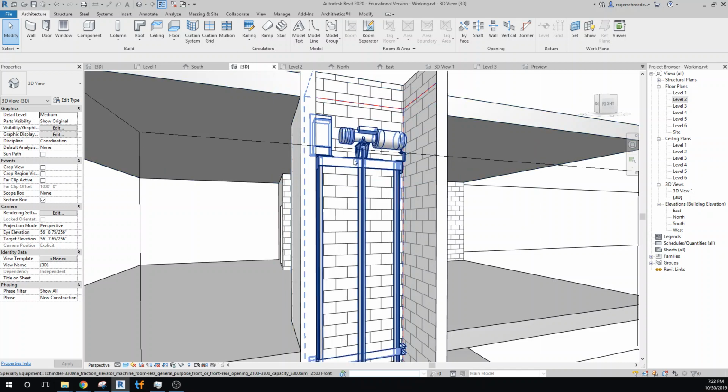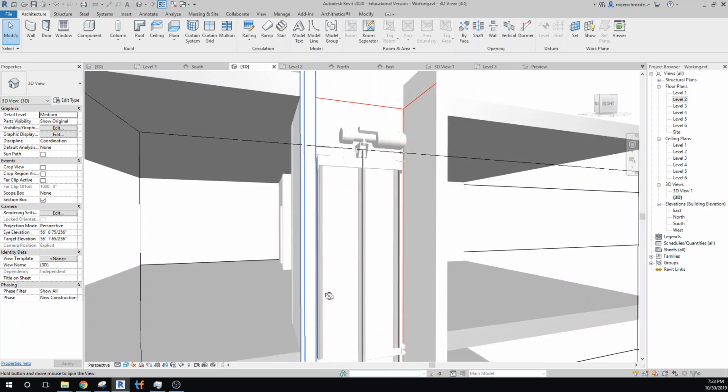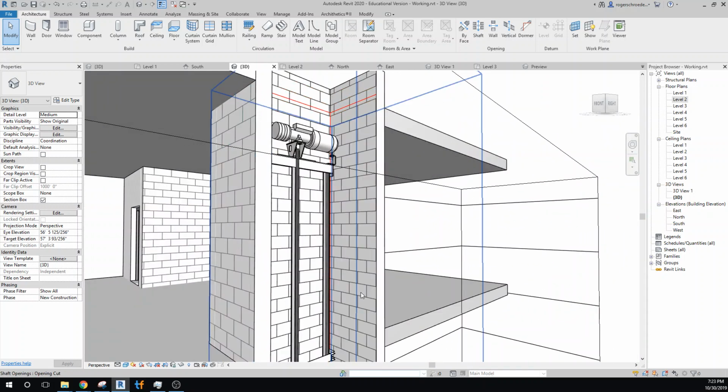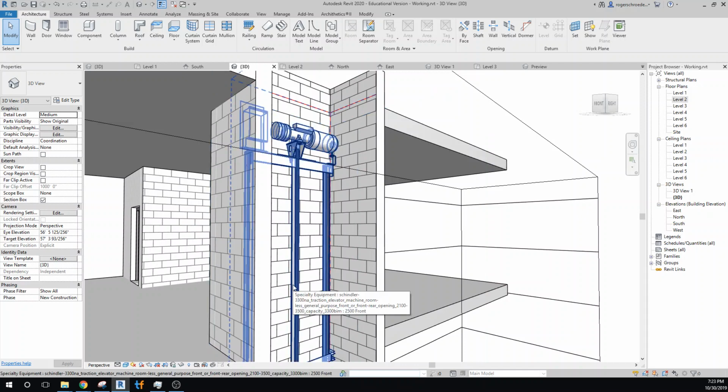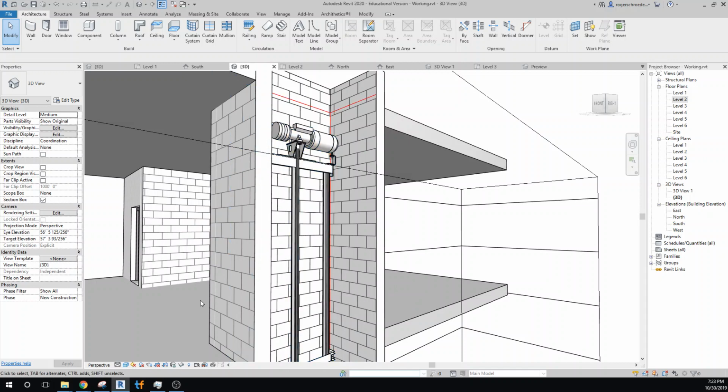Okay, so we don't have any elevator doors yet, and we might just start by making a generic door, and then starting to work back. We'll start with the BIM model that we had, the single speed opening door, whatever it was. We'll see if we can modify that to function as a door element. I'll experiment with that a little bit, and we'll pick it up on the next recording.